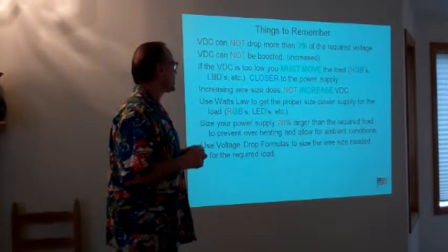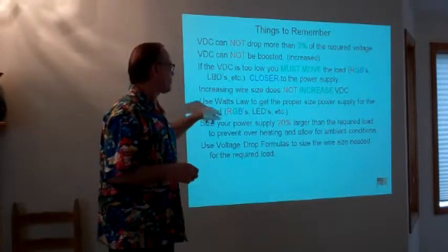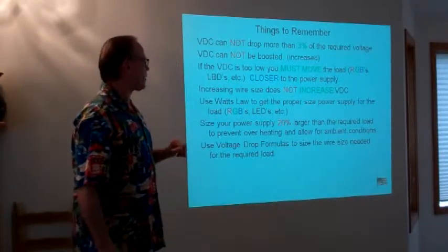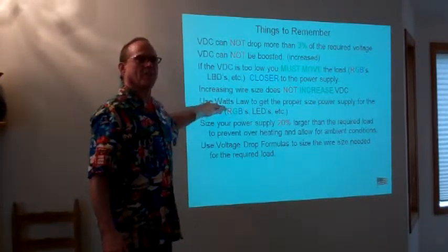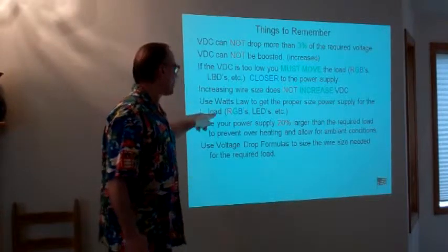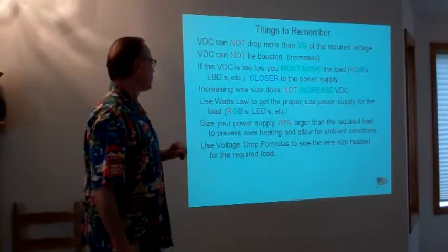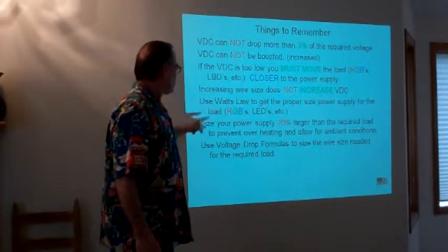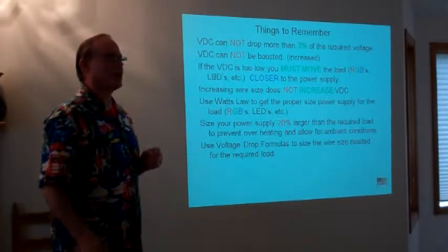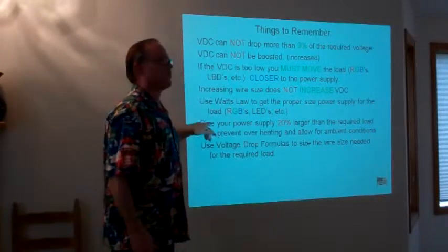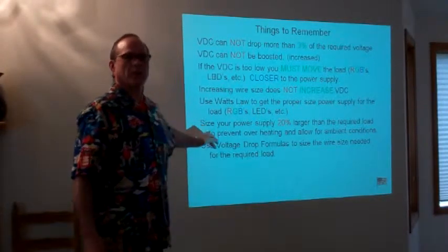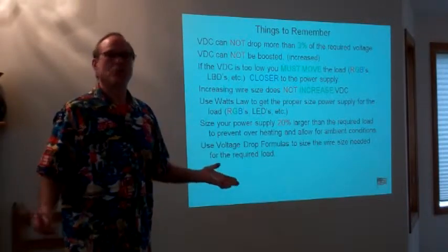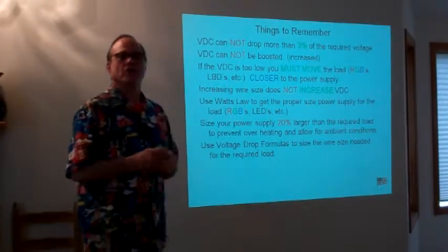You cannot increase it. Watt's law, we've looked at that a little bit there. We've been able to size our power supply using that, and we've also been able to figure out our loads based on that. Watt's law is very useful to us. Size your power supply 20% larger. This is a rule of thumb. If you feel that you want to make it 10%, that's up to you. 20% is my rule of thumb.